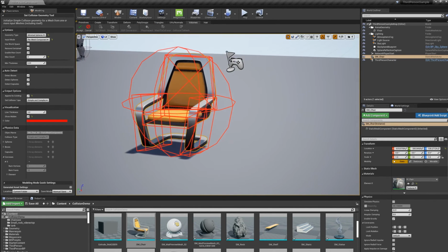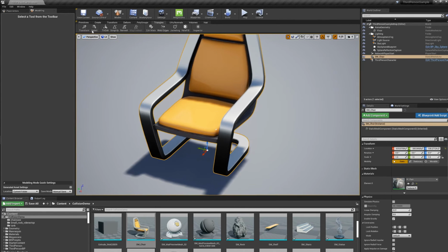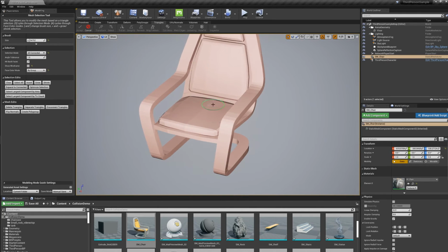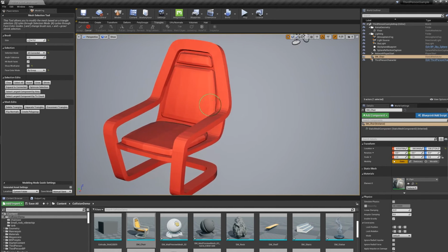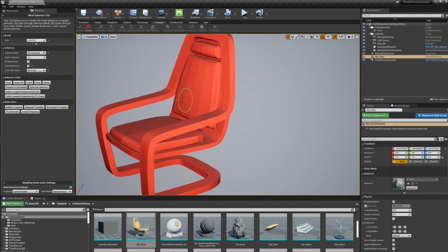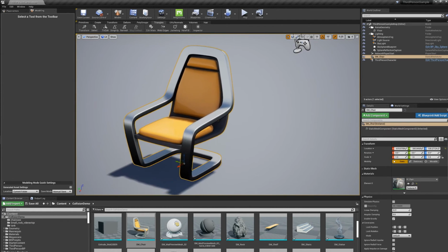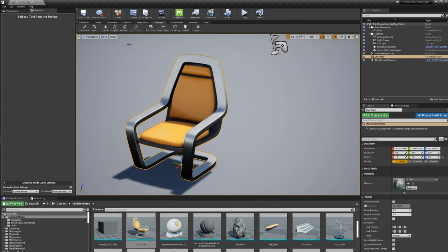There's only one. The other thing that's tricky about this mesh is that it's all merged together. So if I go into Selection Tool and select All Connected, what you see is that the whole thing is connected. So these pieces have been Boolean together, these separate base and back, or even maybe hand authored as one single piece. And so a lot of our tricks that we use so far won't really work. So what I'm going to do is make a duplicate of this chair, and I'm going to edit that chair in pretty coarse ways, but that's going to be sufficient for collision.